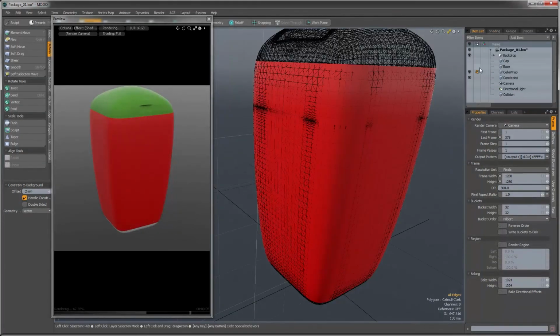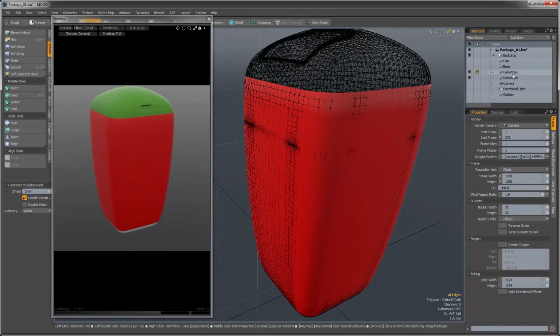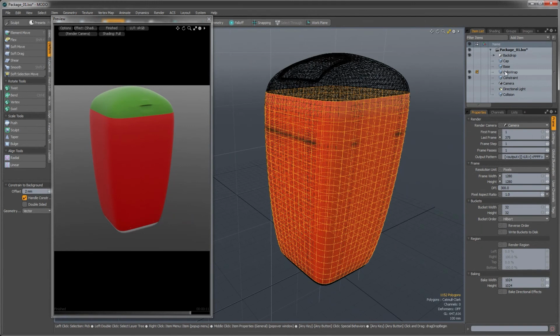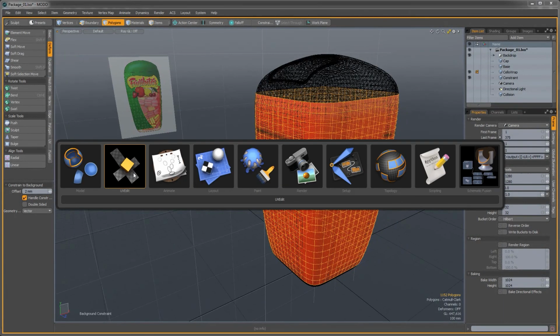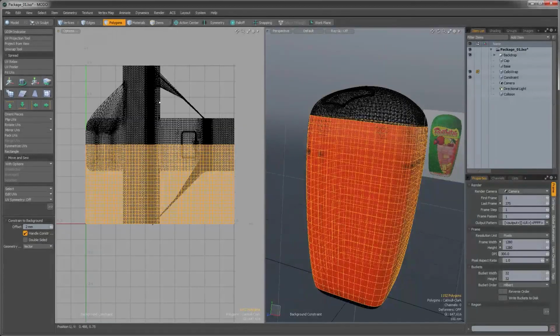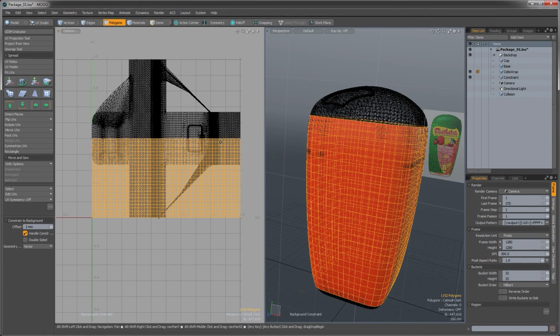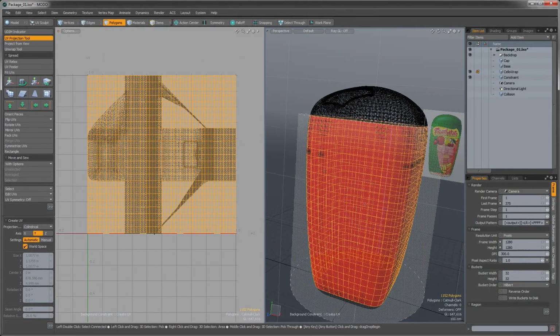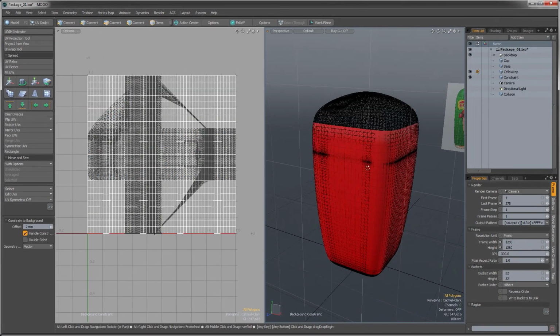All right, so now we're going to take this cello wrap and we're actually going to UV map that. So let's close our preview, jump into our UV edit. So you can see that since that was a cylinder, it had the two caps up at the top here. We're just going to do a quick UV projection, cylindrical on the Y, and just keep that at automatic. Clip in the viewport, and that'll fill this entire UV space with it. So that's really all we need to do with that.